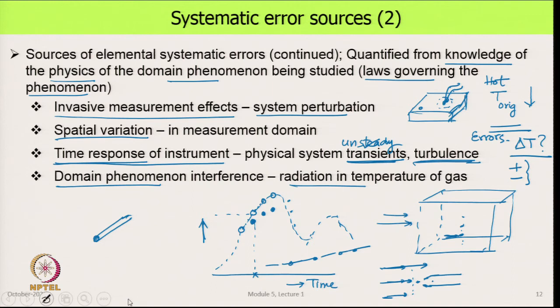So, if we just hold it in the room and say this is the air temperature, well, that is a measurement, but we do not know what are the errors that have come into it. If the room air were cool, say 15 degrees Celsius, and the walls were 30 degrees Celsius or 25 degrees Celsius, then this instrument will not show 15, but 15 plus something. So, whose temperature are we reading? Well, it is not the air temperature, but air temperature of the sensor, which is slightly different from the air whose temperature we were trying to measure.